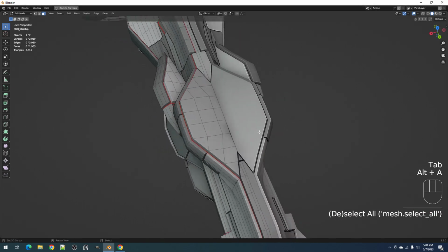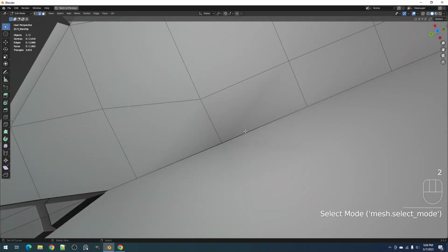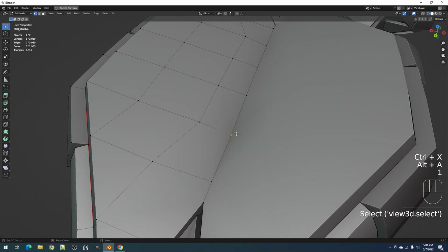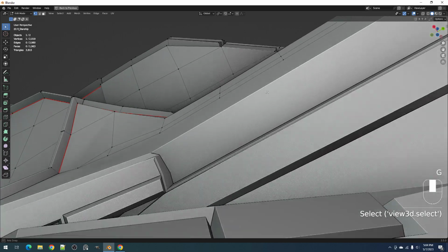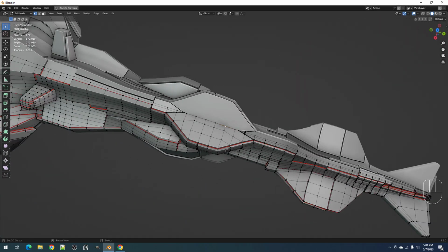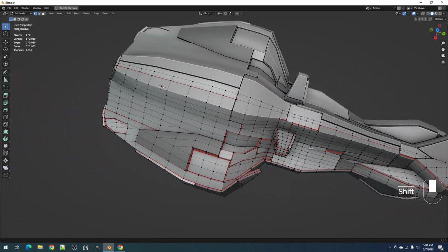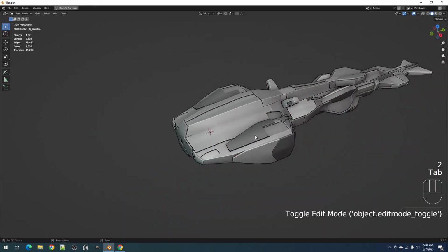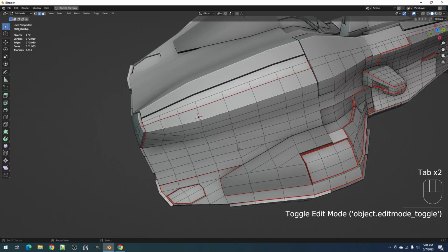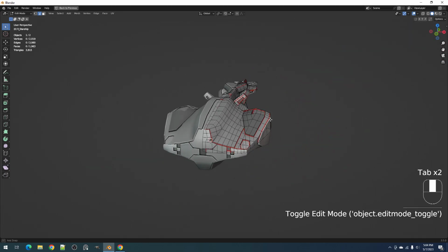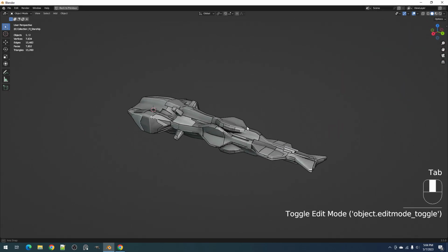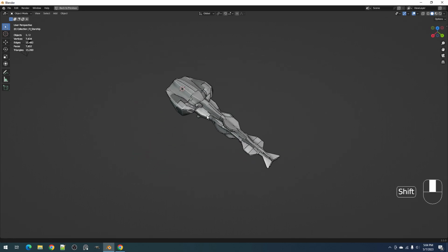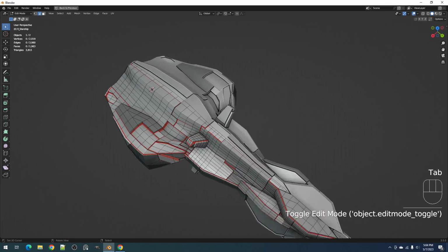there's also some areas that are not going to be perfect because this is, of course, a randomized mesh. Some areas may have problems with their topology, so it's up to you to repair that if you see that, because sometimes the details can go chaotic on some areas, so watch out for that.